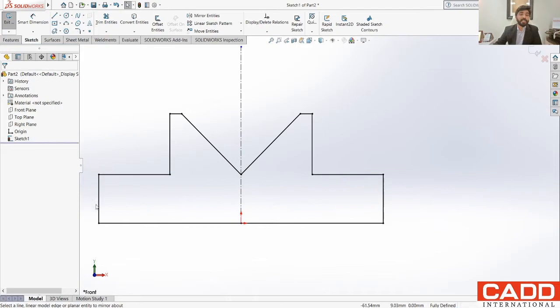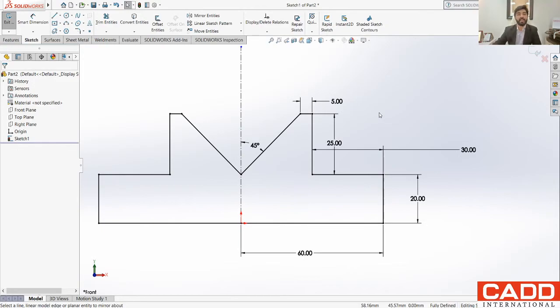Now all the sketch dimensions are hidden. You also have the option for view sketch relations. If you activate that, these are the relations. These relations were not turned on, so it is better to turn off the relations. And whenever needed, you can turn the dimensions off also.